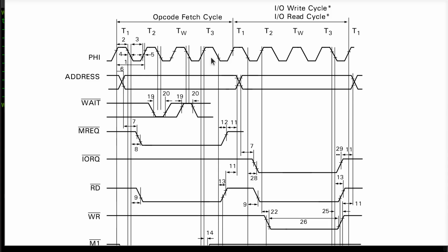Read. And the Verilog is designed to continuously read values out of the memory inside the chip. Does it really matter? I'm going to get the same value 3 times in a row, and all will be well. That's why I didn't bother synchronizing it to only one cycle. Same can be true for I/O devices, and I actually do that in an older version of my code as well. However, if we were to create an I/O device and we want the I/O device to have some knowledge, like a self-resetting flag in a register that says once you've read it, the flag will reset itself.